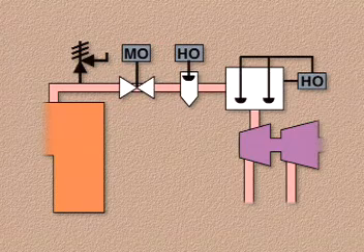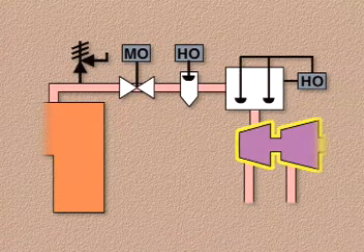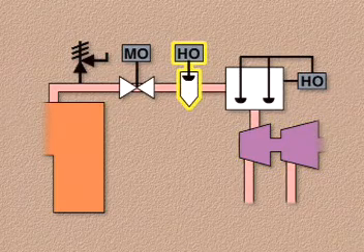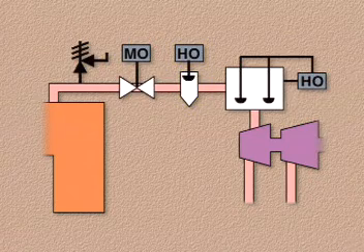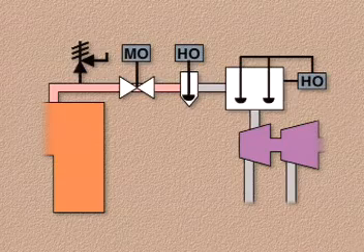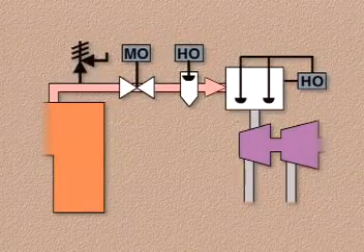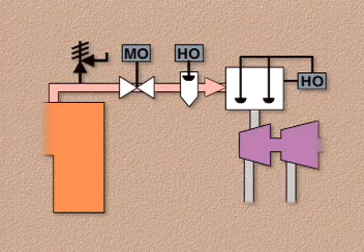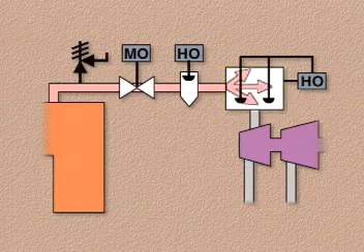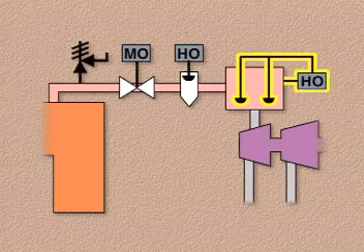The main steam stop valve safeguards the turbine from overspeed and other potentially damaging conditions. During normal operation, the main steam stop valve is fully open. But if the flow of steam needs to be shut off for any reason, the valve quickly trips closed to stop steam flow. From the main steam stop valve, the steam flows into the steam chest. The steam chest is a collection area designed to distribute the steam to the hydraulically operated turbine control valves.